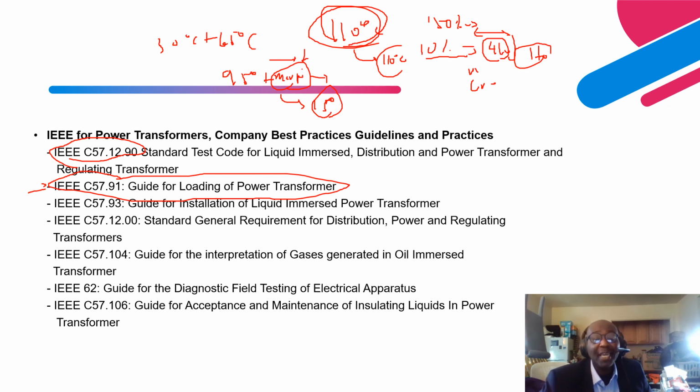To prevent heating of the paper insulation and also heating of the oil. What it's going to do is degrade your insulation, and your insulation strength is going to decrease, and basically your degree of polymerization, the strength of the paper insulation, is going to go down.